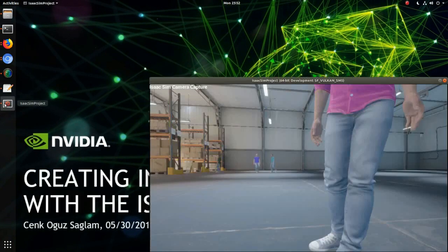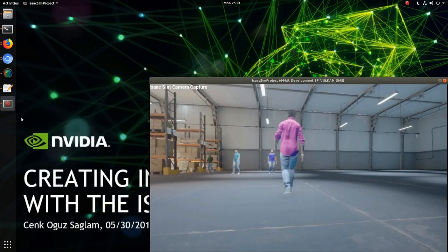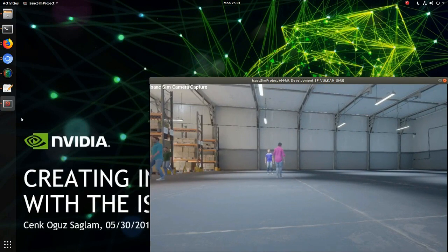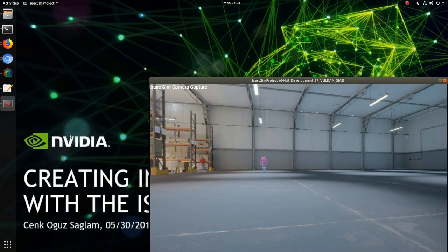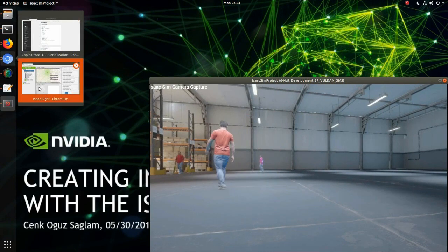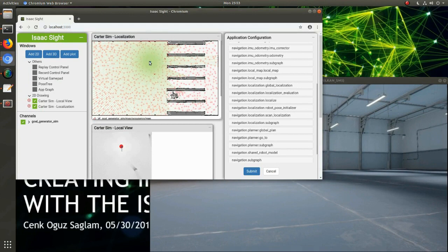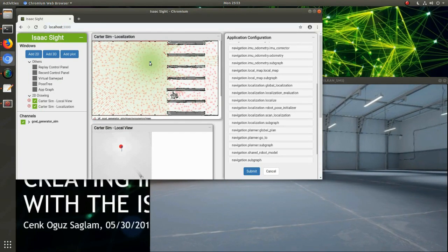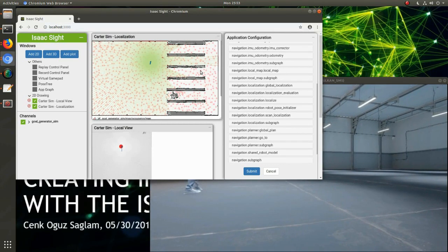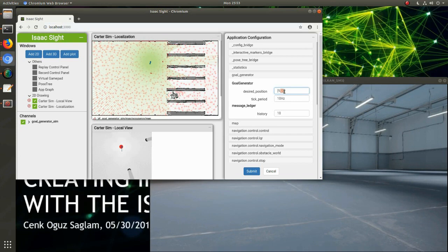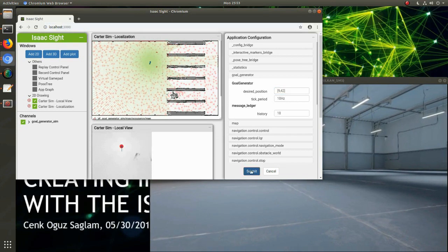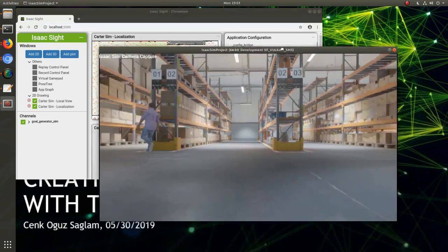Let me show you what you'll be able to do at the end of this webinar. We are looking at a warehouse simulation from the robot's point of view in Isaac Sim. Isaac SDK is capable of navigating robots autonomously while avoiding people and obstacles. No matter whether you simulate or deploy your application to a real robot, Isaac SDK provides you with a visualization tool called Sight. On Sight, you'll be able to track your robot's vision, localization, goal, and plan among other useful information. Using Sight, we can also change parameters. It seems the robot has already arrived at its location, so let's send it to a location we like. Let's go to the goal generator and change the desired Y position to, let's say, 42. When we hit Submit, we'll see that the robot starts autonomously navigating to the location that we send through the